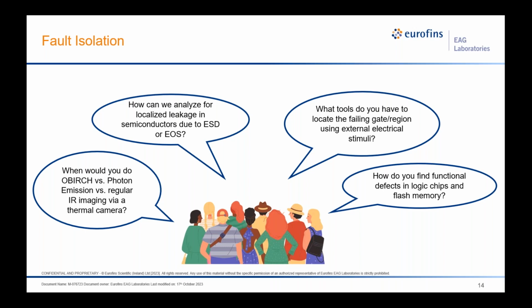Photon emission is like you're treating the device like a black box. You're comparing a failing device with a reference device and seeing what the difference is. Where is it? Whether the difference is in the block that you suspected, and then you zoom in, it gives you maybe a block of different size, and then you combine other techniques, whether you add internal nodes to do microprobing or nanoprobing, or all kinds of voltage contrast combined with delayering, at a different level.